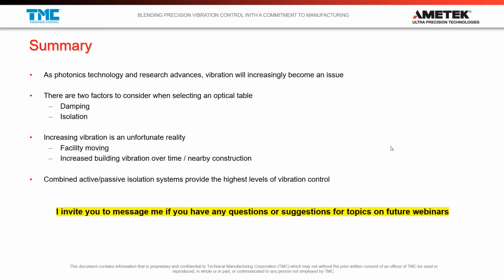And if you really need to get to a place where you need the best vibration control, especially for photonics applications, you want to combine your active and passive systems to benefit from both the low frequency performance supported with a serial type piezo based system and the high frequency performance from the passive isolators. And that's the end of the webinar. If anybody has any questions or suggestions for future webinars, feel free to contact or reach out.